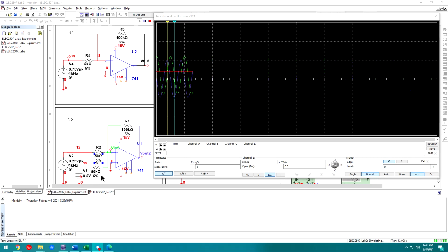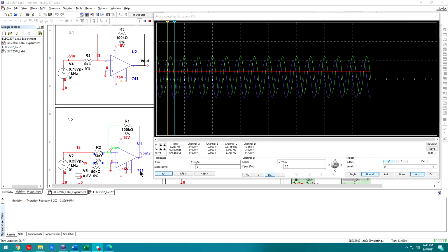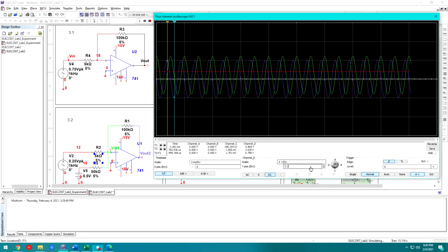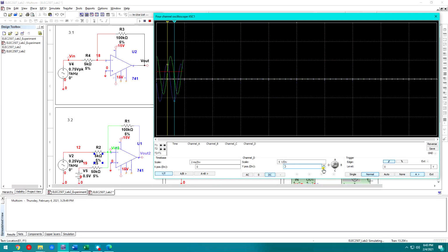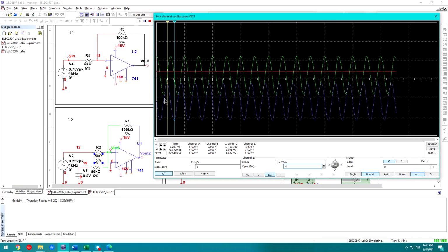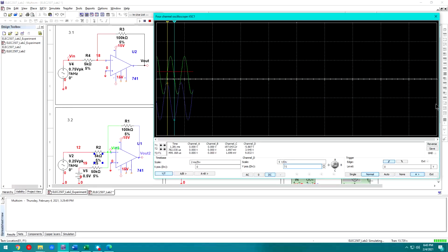So if the DC portion of the output is getting amplified by a factor of 2 here, that would mean, -2 actually it would be, then that would mean the center of the output waveform should be technically at -1 volt, right? The center of that waveform.